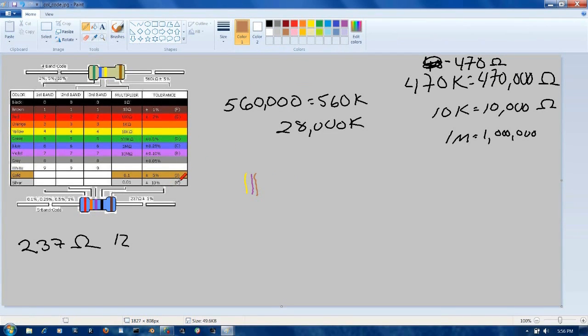And gold. Well, we'll use the same color for that. And assume this is gold. And so you would be looking for a yellow, violet, brown, and we're actually going to use a 470 ohms resistor in our first circuit. And we're going to actually see in this tutorial how we figured out to use a 470 ohms resistor. So now this is the reverse. We figured out the colors we're going to look for in our parts bin to find our 470 ohms resistor. By the way, the larger the number, the more resistance.